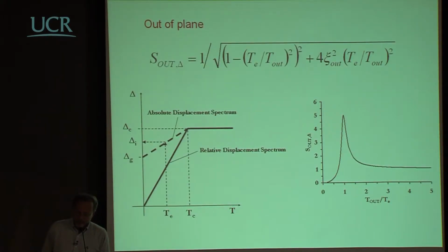So first of all, looking in terms of what the demand will be, imagine that you know the displacement spectrum coming from the earthquake, the one that you have at the base of the wall. Now, if you think in terms of this displacement spectrum up at the first, second, third floor, and so on, you have essentially a filtering effect, which is due to the combination of the two periods of vibration: the period of vibration of the in-plane structure, and the period of vibration of the out-of-plane structure.